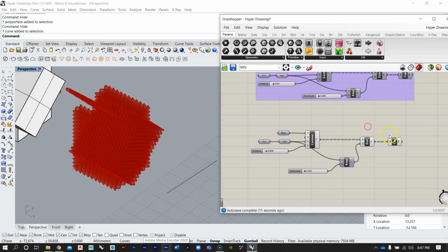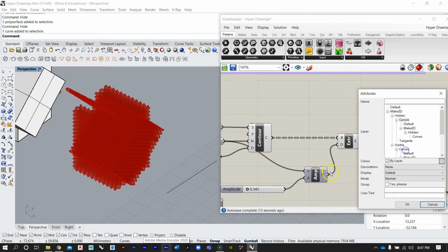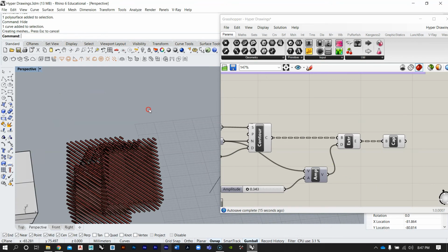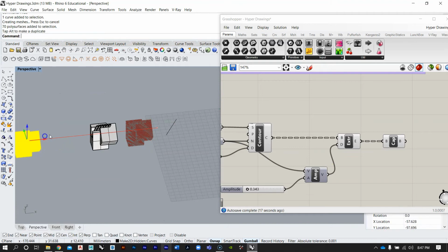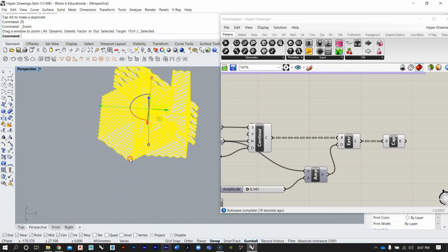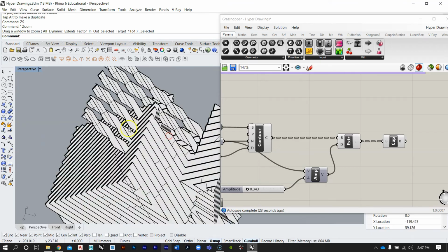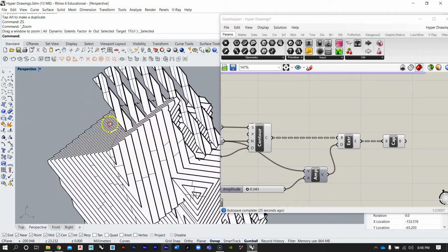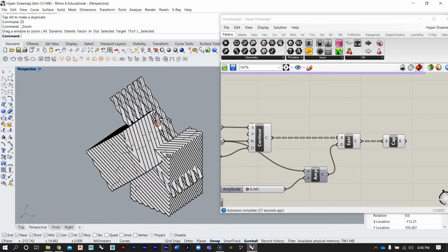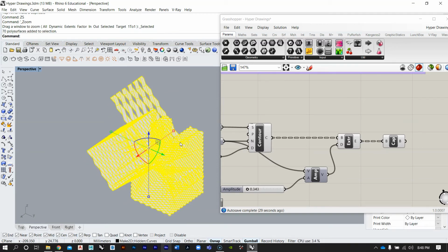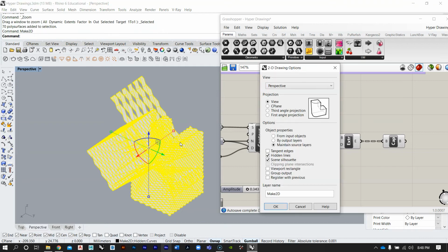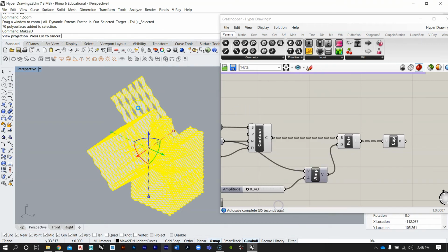Okay. And then I can right click, bake, and get that geometry. And then I can do a make 2D of this and get something interesting as well, right? Where the geometry is now shifted or changed slightly from the base massing of the input. So I'll do a make 2D of this, click OK.